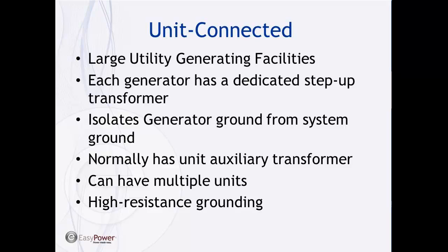And the basic principle, what defines a unit connected generator, is that each generator has a dedicated step-up transformer, and that's going to be a delta-wye. So that's going to isolate the generator ground from the system ground. That gives us much better protection, and much limits the probability of having to deal with system grounds that can affect the generator.